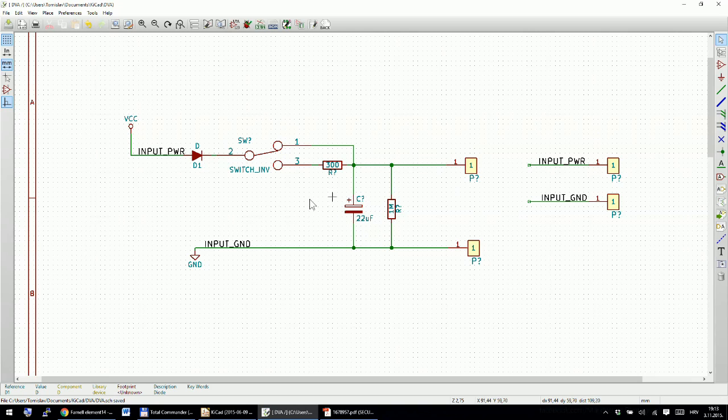In this case, I will, in some places, and I usually do things when I need my components named logically. Let's say I have a switching regulator on one side of a board or something else. I give names to components so that when I check my PCB after a year, there'll be a logical naming of components. Let's say I will number the resistors in one part of a circuit 11, 12, 13, and on another side of a board these resistors will be named 22, 23, 24. So by number somehow I will know it.